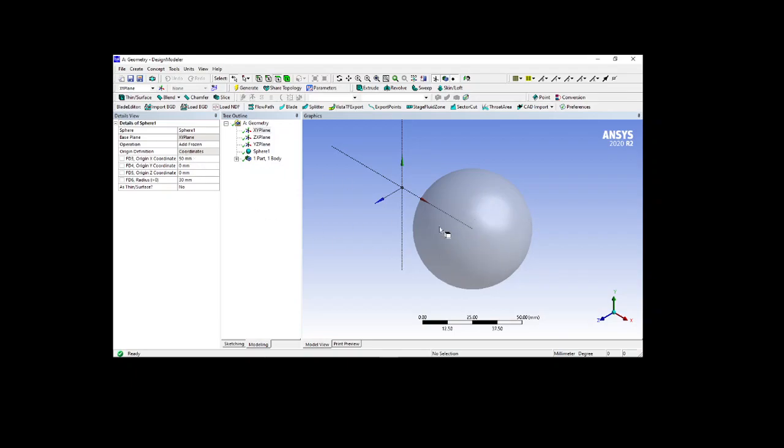Then if you want this inline option, it should be at the plane that is 50 of our y-axis also, then you will get this. Now this is our xy plane. This is 50 mm of offset of x-axis and 50 mm offset of y-axis. If you want to take it into a z-axis, then you can also print 50 here. This is how it will be.